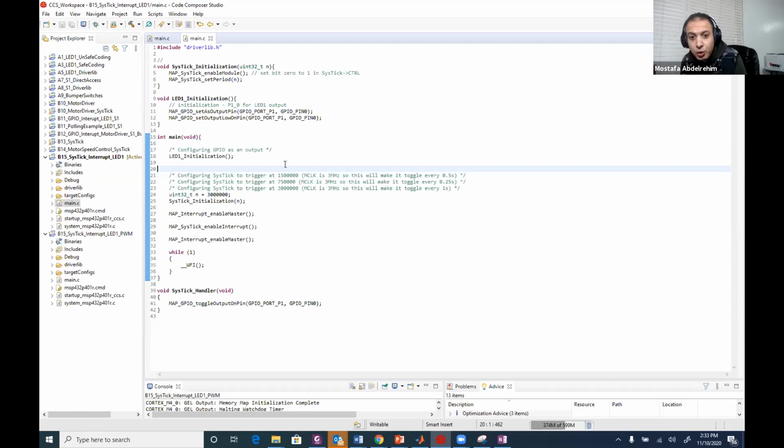Today we're gonna learn how to trigger a SysTick interrupt from that module. Basically, this interrupt is really simple. This is a timer. You load the timer with a maximum value. The timer will start counting down from this value to 0, and when it reaches 0, this will trigger an interrupt. But of course, you must handle this interrupt. You must write an interrupt service routine and make some configuration also so that this interrupt will actually cause the interrupt service routine to execute. Okay, so it's simple. It's not hard.